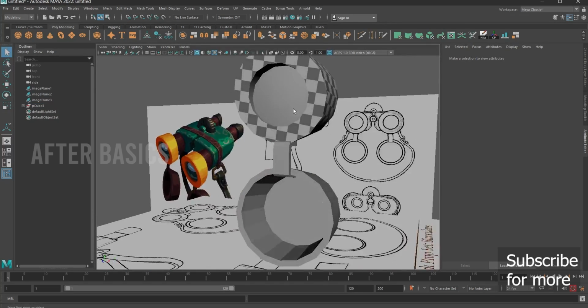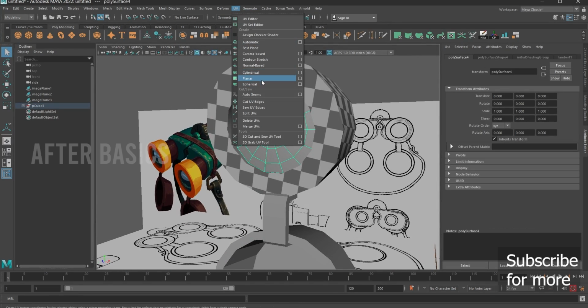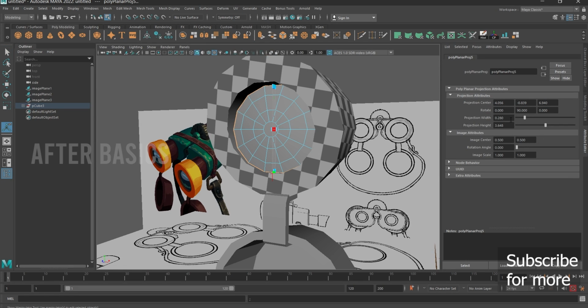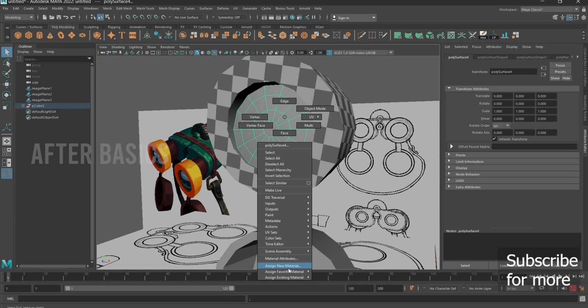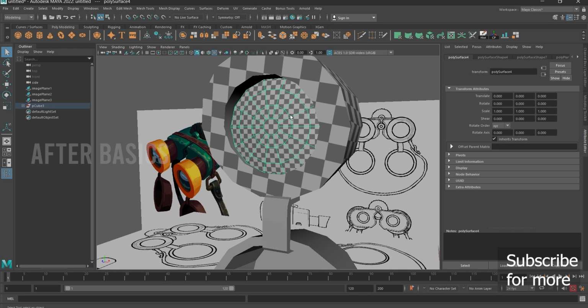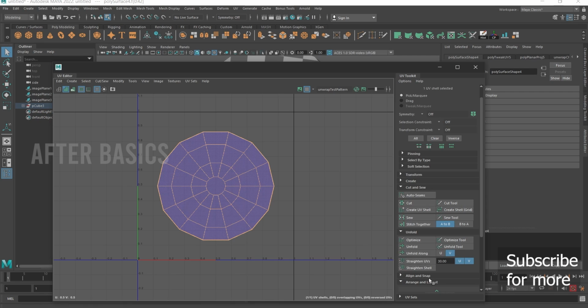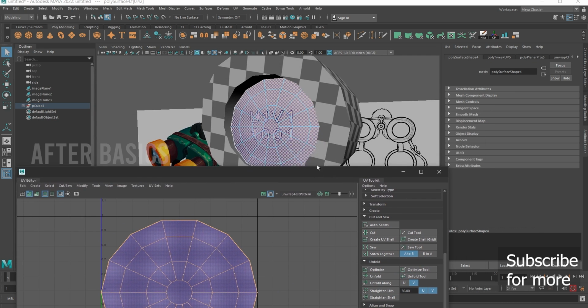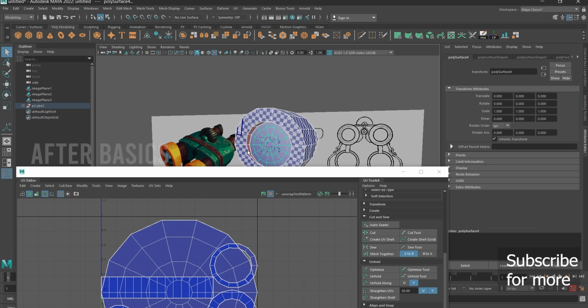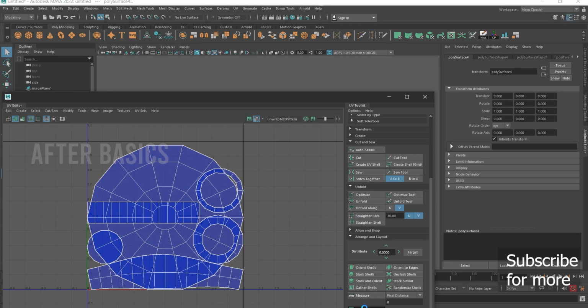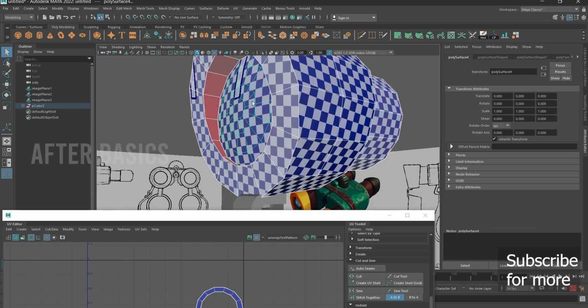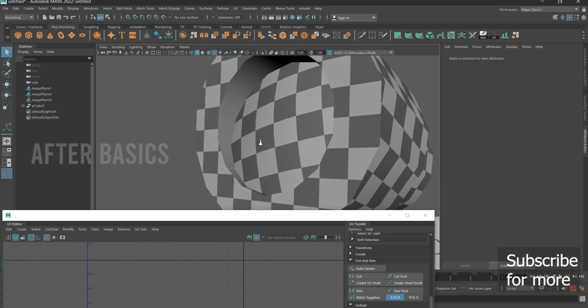Okay, every part here. For this part we can actually use this UV planar method. So use 5 and 5 here, 0 here, and we are done. Okay, so existing, I think, checker shade. Okay, so see, we get this part. I'm gonna go to this UV editor, then I'm gonna unfold it and put the layout in there like this. Okay, so let's select both of them and layout. So see, everything is in correct way.